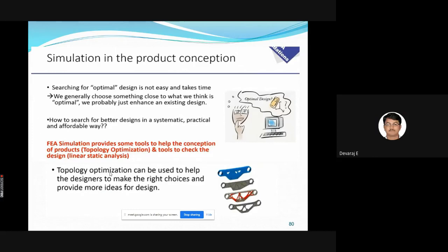Yes. See, fatigue indicates that you keep on applying variable loads, fluctuating loads, to the object. So here, for a bracket used for connecting the TV, only static load will come into picture, right? So there is no dynamic load. Dynamic load means fluctuating loads, that is called fatigue loads. If you keep on applying different loads to the material, that indicates fatigue. So here fatigue will not come into picture.